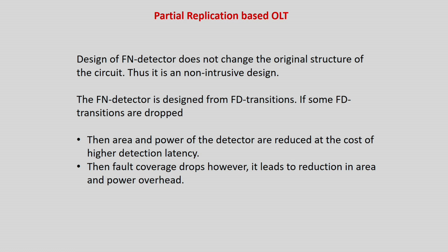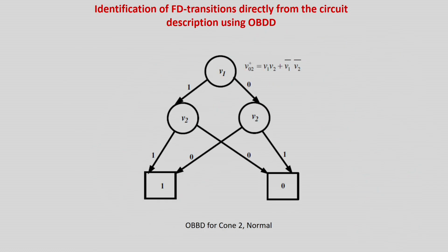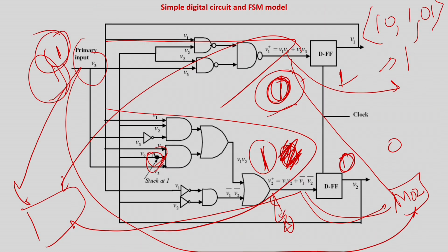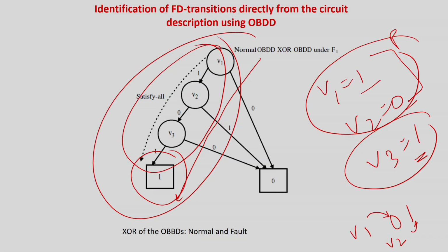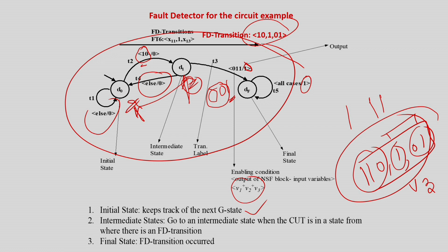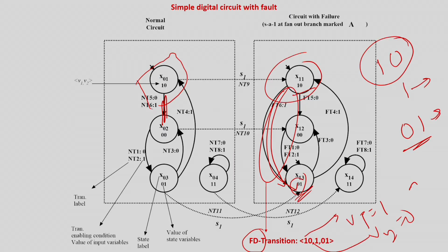the other counterparts. So basically, what I have done, I have taken a circuit either represented by an FSM model or by a BDD. I find out the FN detector and I represent a fault detecting detector which is going to be synthesized as a circuit to do the online testing. But this circuit is not very small compared to the original finite state machine. So the FN detector or the tester will be very comparable with the CUT.